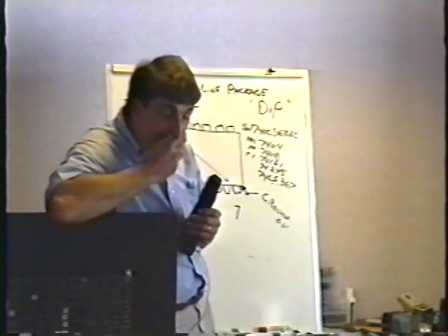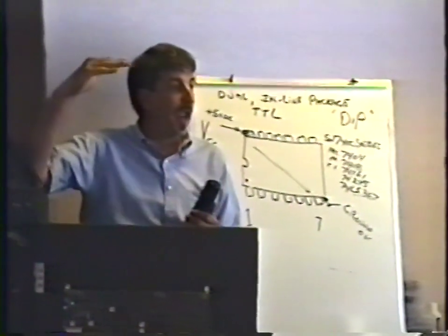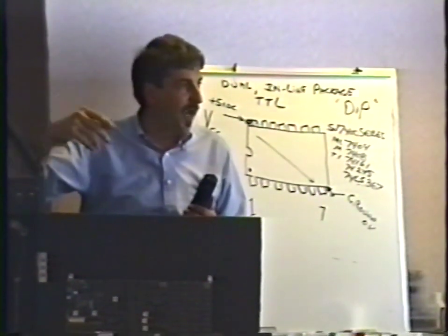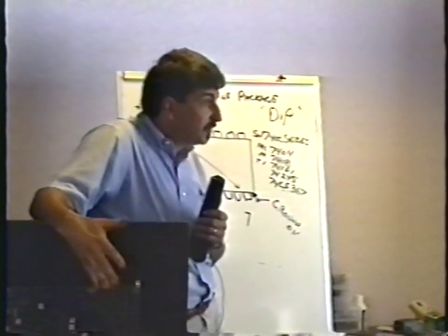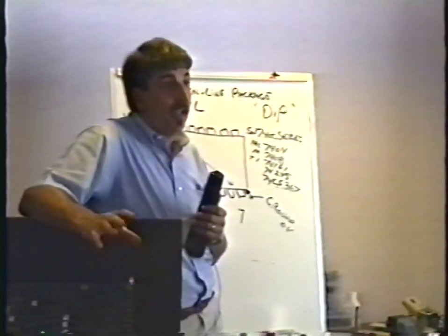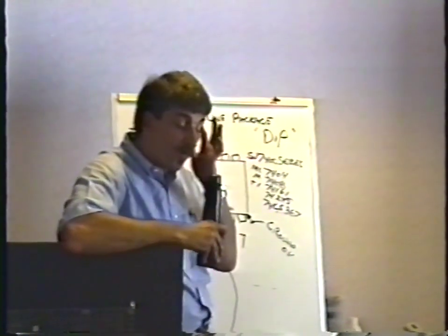Many games have a self-test in them. You've probably seen it. You fire up a game, it says ROM okay, RAM check, or whatever. If it tells you that one of those devices, one of those ROMs or something that's in a socket, is bad, it may be that, or it may be some other chip, but you certainly want to try that first.